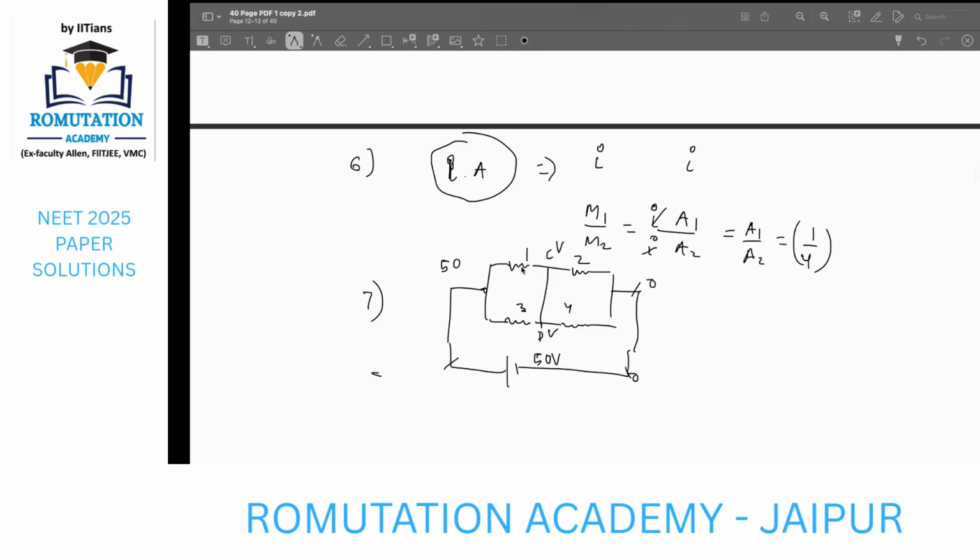I can apply the Kirchhoff circuit law, or the current law, which is better, assuming all the currents to be outgoing and summing them to be equal to 0. If I treat this number as I, then I plus (V minus 50) by 1 plus (V minus 0) by 2 is going to be 0, right?